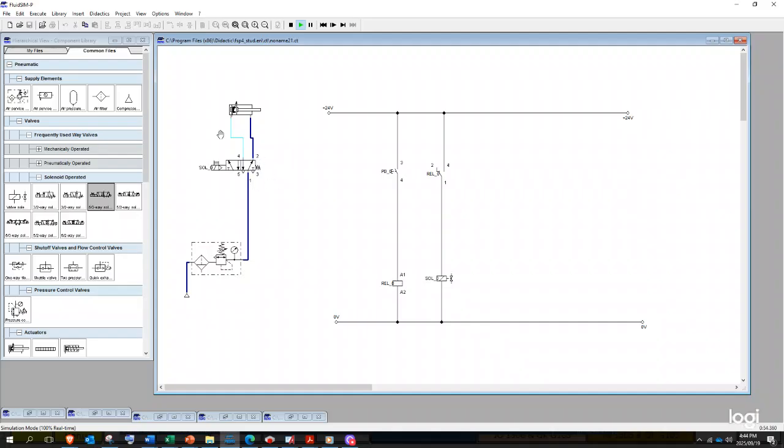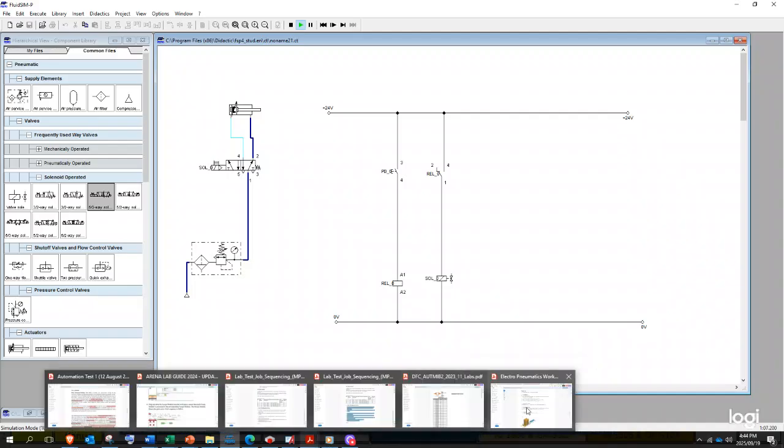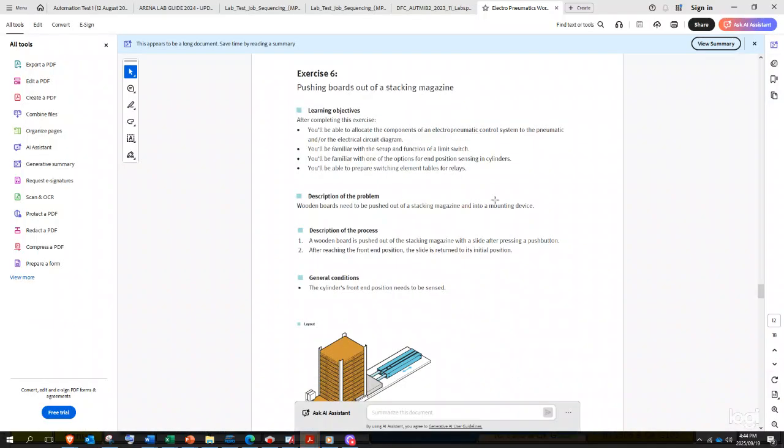In the previous example, the spring effect was coming from the single acting cylinder with the spring return as well as our solenoid valve. So we are able to achieve what was required of us by presenting it in 2 different methods.